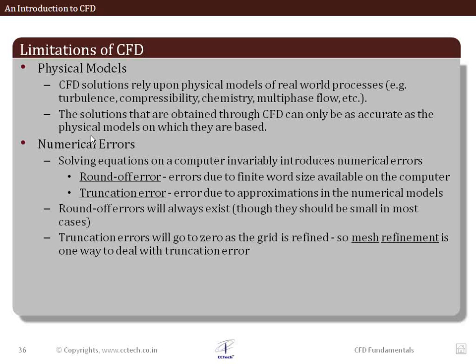Truncation errors are because of the numerical method. Let's say we define the solution of a problem using a numerical method. A partial differential equation is being broken down on a discretized geometry in a discretized form. There are some orders of accuracy that we obtain by neglecting certain terms for the sake of simplicity, and in the process we end up having some truncation errors.